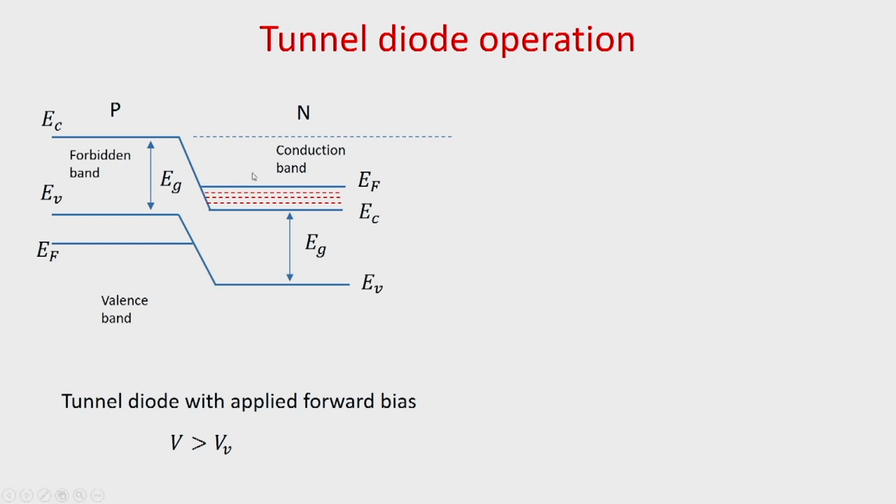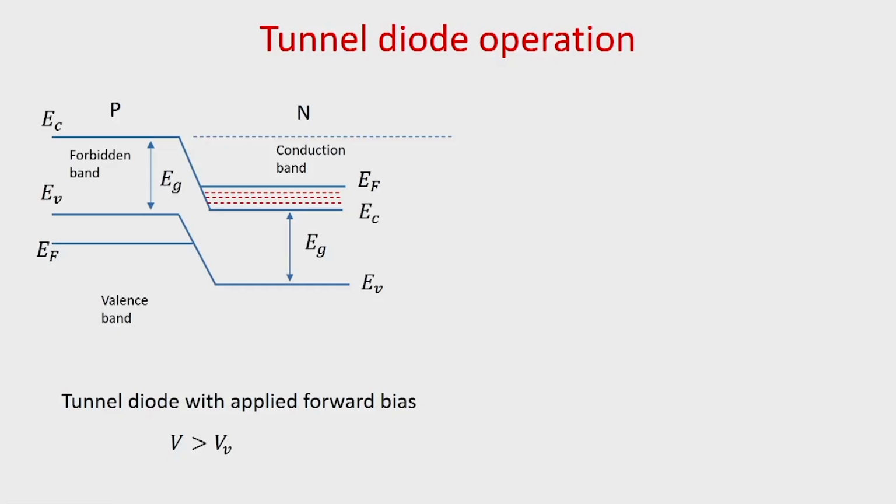move over this potential barrier if these electrons are to migrate to the p region, and therefore, the normal carrier injection mechanism starts taking place, and therefore, the tunneling of electrons actually takes place over certain range of applied voltages, and this phenomena will happen only when the p and n sides, they are very heavily doped, favoring a situation where direct tunneling of electrons can take place.